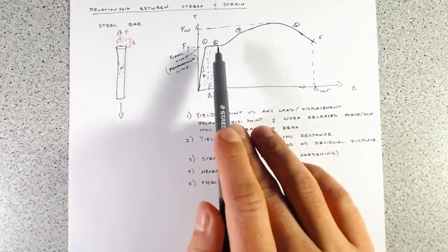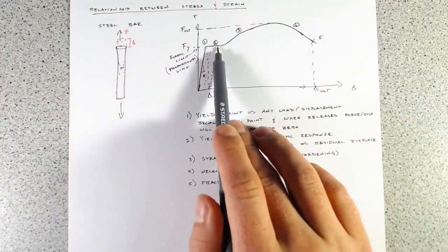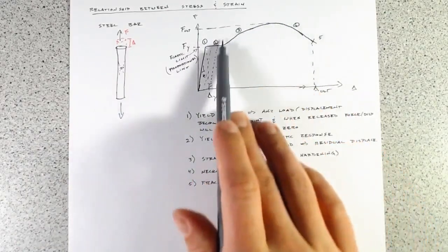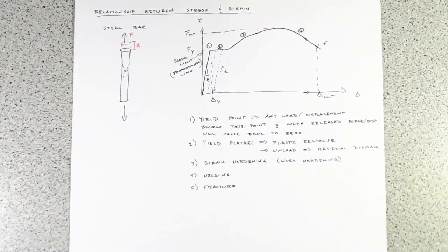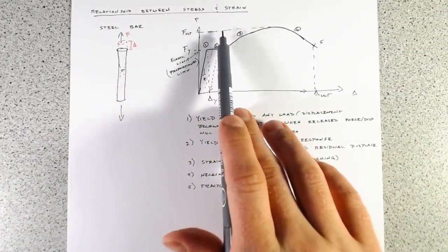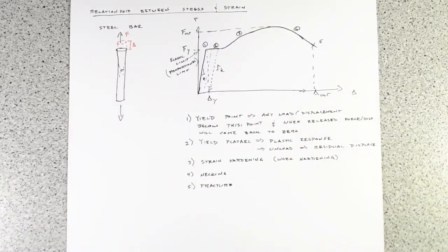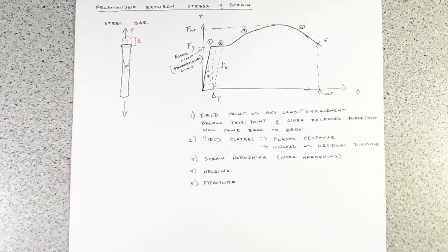And then we've got all of this extra deformation capacity, which we hold in reserve in case we have a bigger load than we expect. We also have additional force capacity, again, because we want to deal with uncertainty in our structures. We don't want to have this come down on someone's head and hurt somebody. So that's why we can account for all of these buffers.